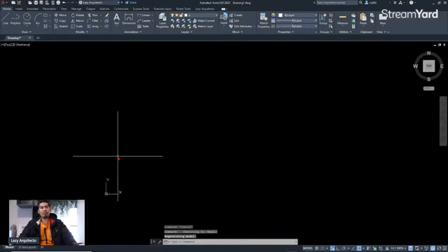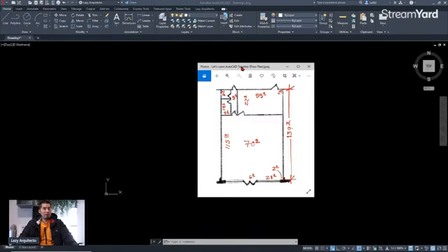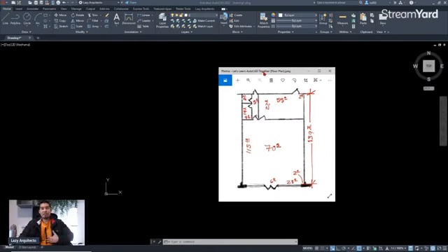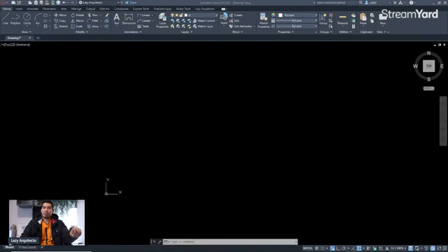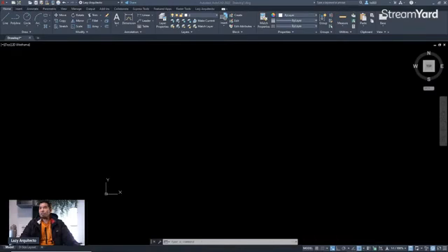All right? Okay, so going back to our floor plan, which is gonna be this over here. One of the first things that we need to do, or that I like to do, is bring this floor plan inside model space. Now, other people like to have it open in a second monitor, like I have it right now. But if you don't have two monitors, of course, you cannot do that. So what I'm gonna do in this basic tutorial on how to draw floor plans is to bring it here inside AutoCAD. Okay, so let me show you how to do that.